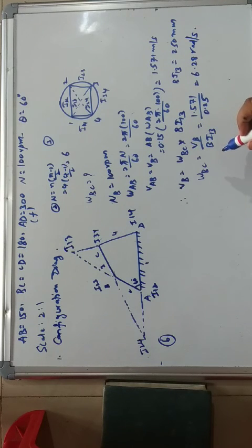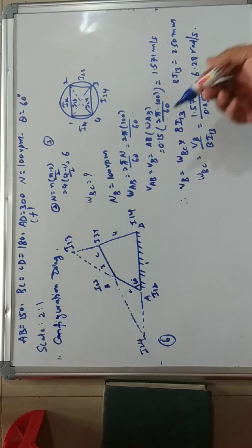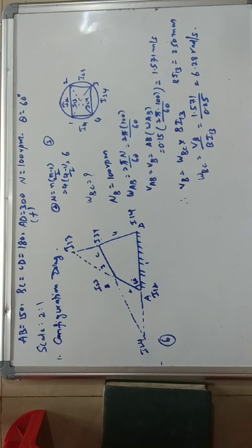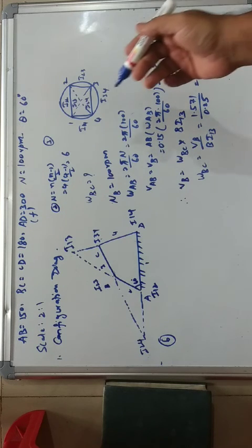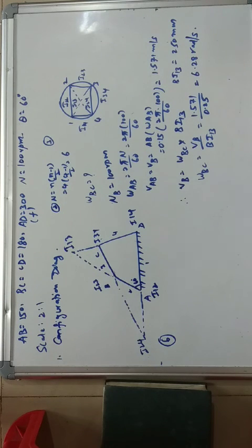In this way we do the velocity analysis, and at the same time we learned how to locate the instantaneous centers. Generally, you can follow either the circle method or the bookkeeping method to find the linear velocity or the angular velocity of the given links or mechanism.